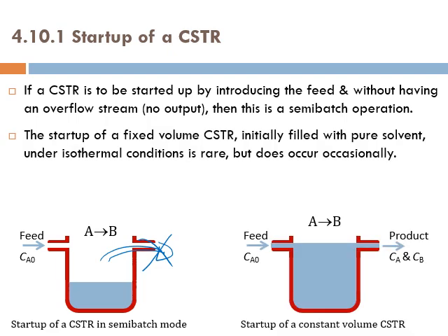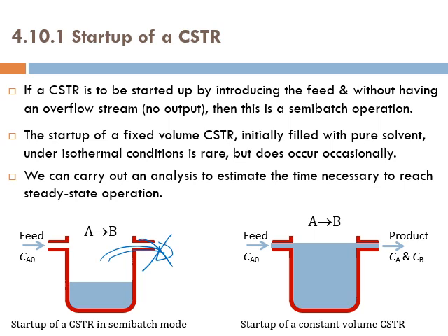The startup of a fixed volume CSTR initially filled with pure solvent under isothermal conditions is rare but does occur occasionally. So now you can see that we have 2 modes of the startup of a CSTR, and as you know, during the startup or shutdown, the operation is an unsteady state operation. We can carry out an analysis to estimate the time necessary to reach steady state operation.